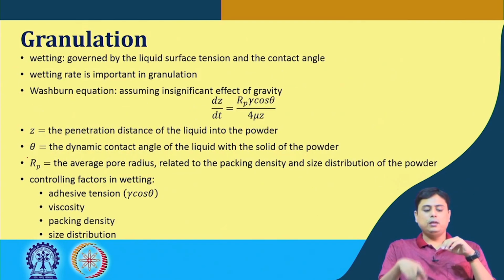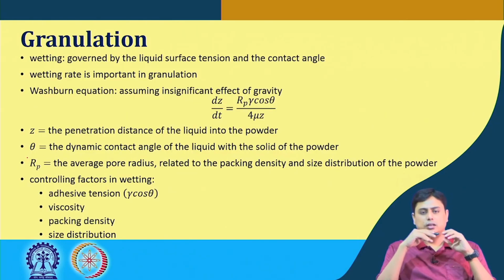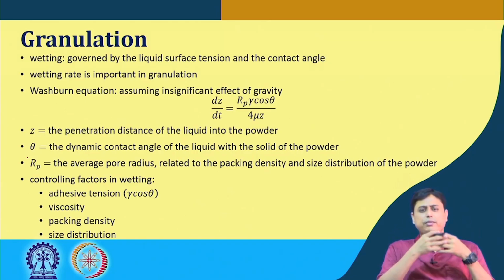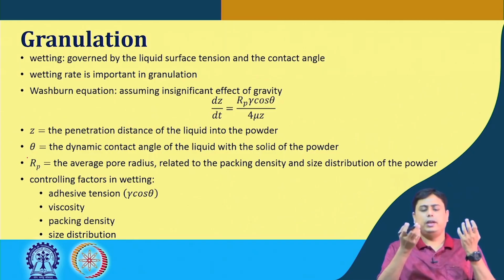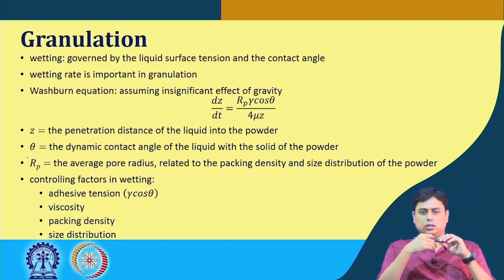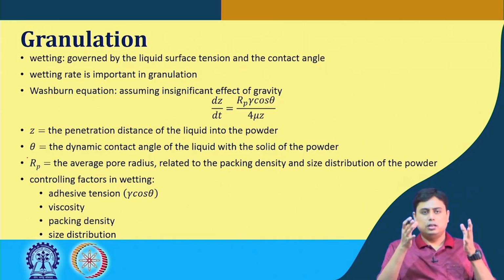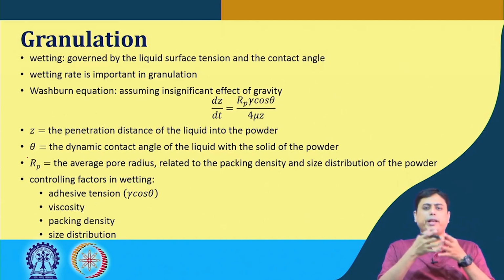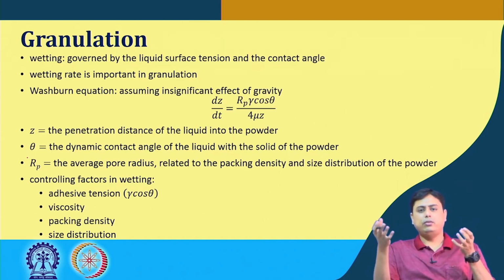So, this wetting is governed by the liquid surface tension and the contact angle of the liquid with the solid surface or the particle surface, and this is a very important step in granulation, because the rate at which this wetting happens dictates how the granulation procedure will be followed.